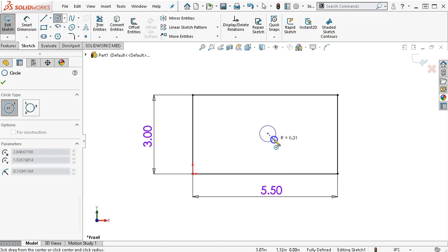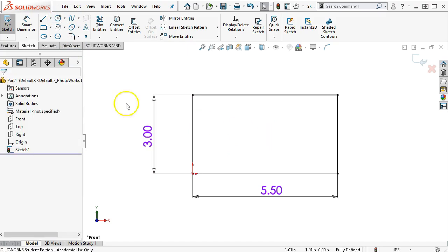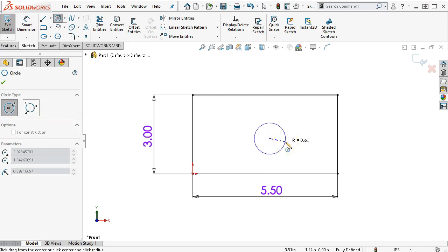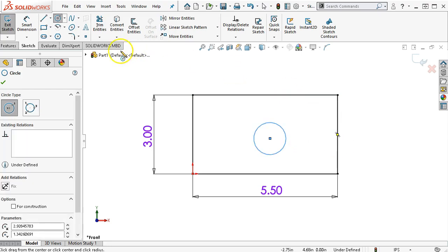And then I'm going to draw the circle, and my fingers were ahead of my mouth again. So we come up to circle and click, and it is showing me the 2 types are the center point and a point on the radius or on the circumference. And then there is a perimeter circle that is 3 points on the perimeter. So I'm going to stay with the click click. My natural tendency is to click drag, so these first couple I'm going to illustrate with click click. So click the first point, drag out some distance, click the second point, we have a circle.